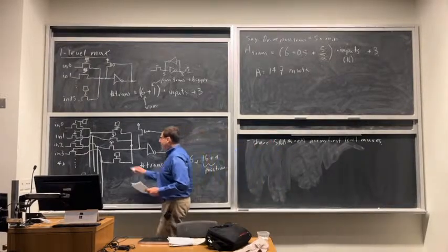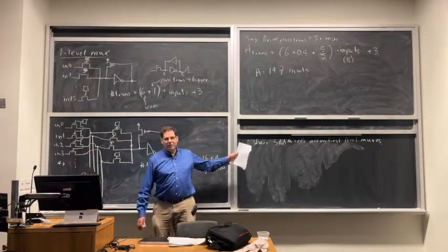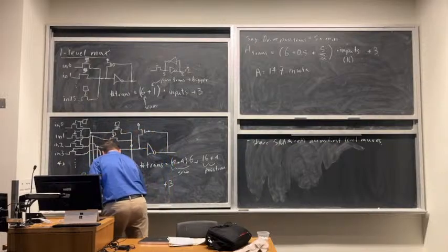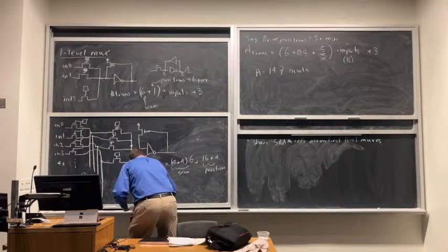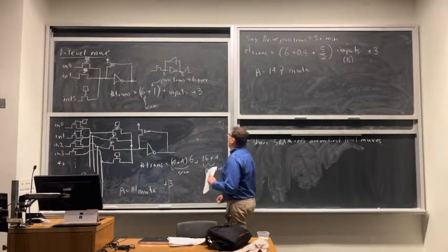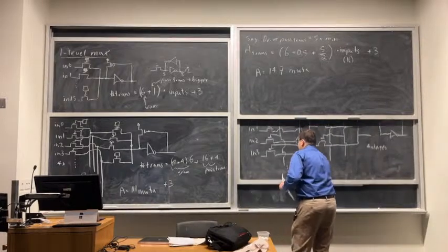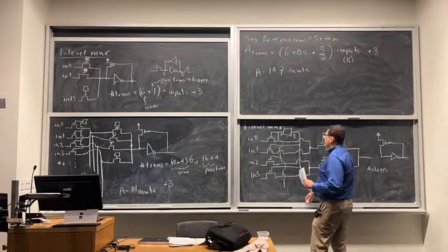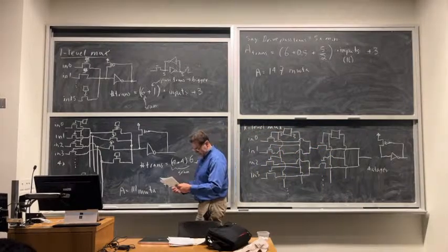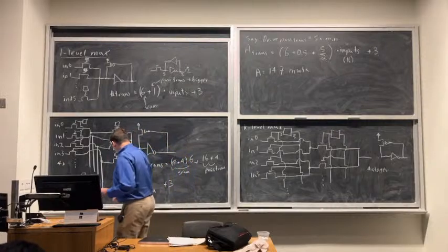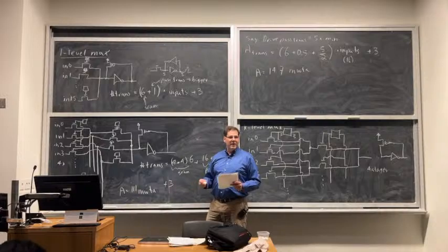If I make these pass transistors 5 times the minimum drive strength like I did before, I use my simple area model for transistors, I plug all the numbers in, I will get the area of this is equal to 111 of these minimum width transistor areas. So let's see. That compares to 147 when we did the fully encoded one, and let's see, where's the number for the other one? Well, I guess it was 123. So this is actually the smallest one. Okay, so this is smaller than 1 level. It's also smaller than K level, so it's a good trade-off.